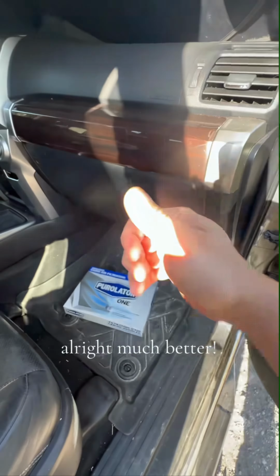If your car is making noise like this one, especially when you slightly step on the brake, come over here. Let me show you what I found wrong with this SUV. Every time the brake was slightly applied, or even at takeoff or rolling at low speeds, it felt and sounded like the brakes were dragging. The reason? As you can see here, the brake caliper pin has dirt and grime built up on it. So let's clean it up, then we'll inspect and see if we can reuse it.